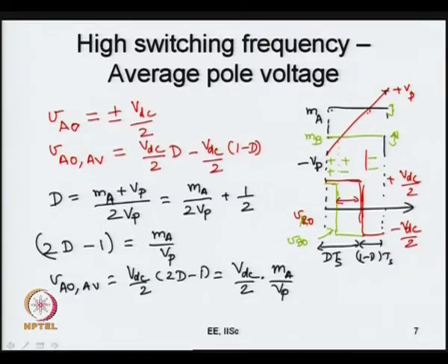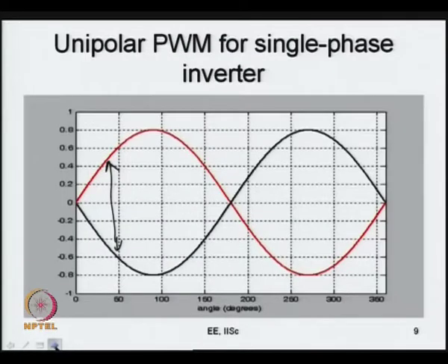So, you can apply 0 voltage to the load either by switching both the top devices on or having both the bottom devices on. So when you are adding common mode voltage, the time for which you are using both the top devices and the time for which you are having both the bottom devices conducting changes. That is why I said it is related to the redundancy. The redundancy is what lets you add such a common mode voltage.